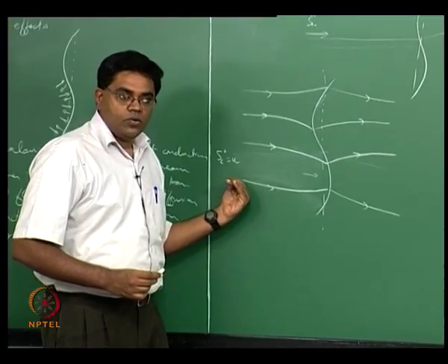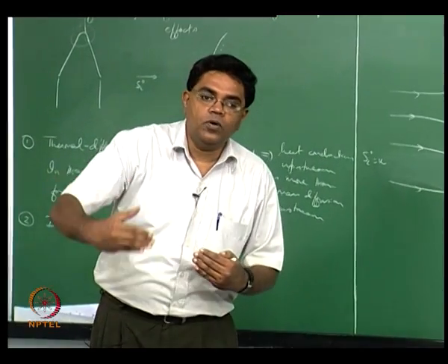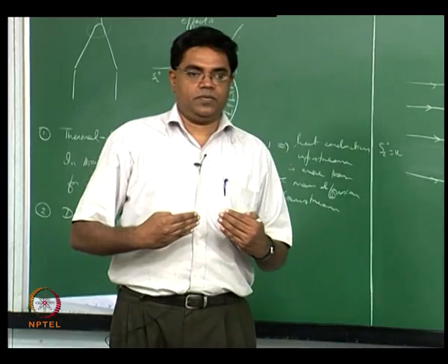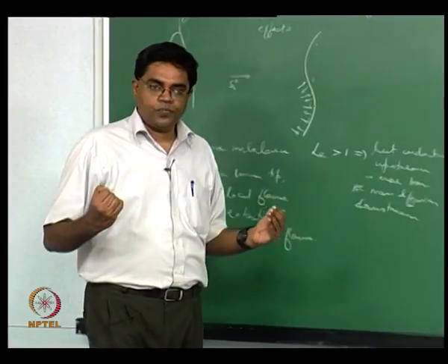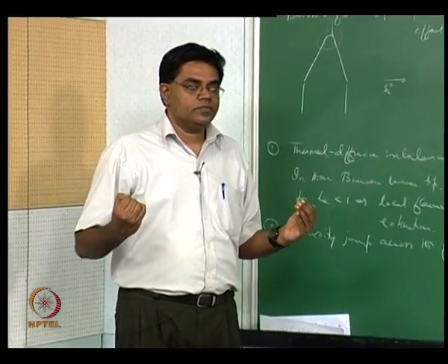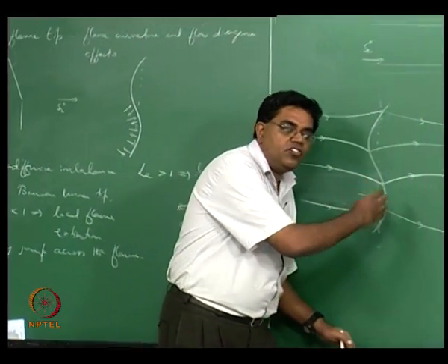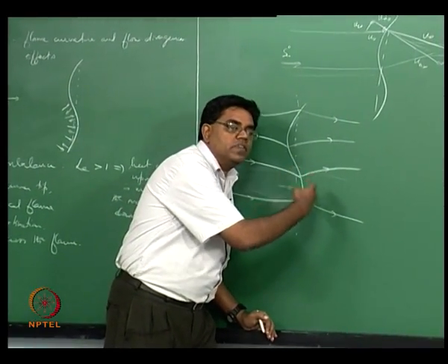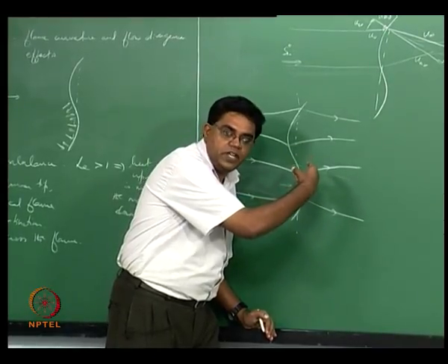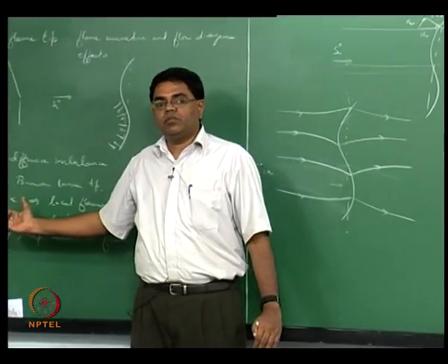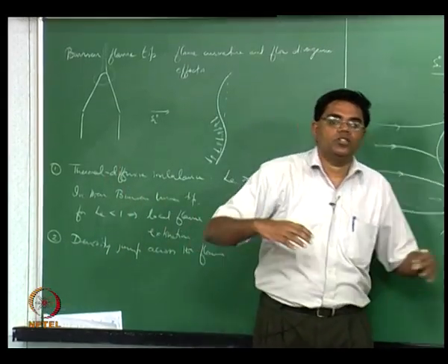So what has essentially happened is the flame has induced the flow to go faster at it when it has a concave curvature. This means the flame needs to compensate for a higher level of increase in flame speed, by a mechanism that we talked about here, if it has to survive. If not, it is going to cause a local extinction.